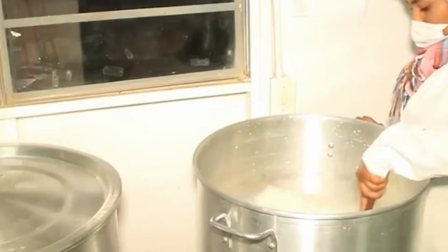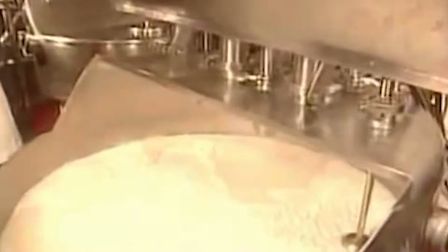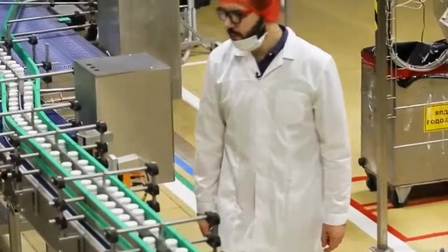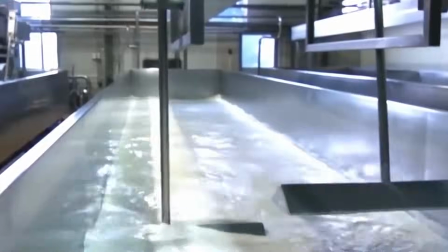The production of frozen yogurt in a factory begins with the preparation of the liquid mix base, which consists of dairy solids, sweeteners, live yogurt cultures, stabilizers, emulsifiers, and water. Each component is handled in isolated supply systems to ensure batch-to-batch consistency before integration. The mix formulation is calculated to achieve a target fat content of 2 to 4%, milk solids non-fat of 8 to 12%, and a final total solids content between 30 and 38%, depending on the product type.